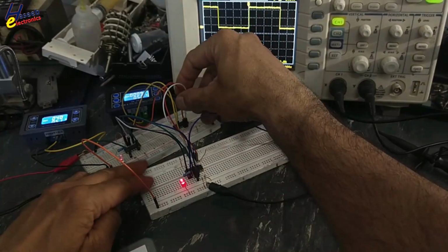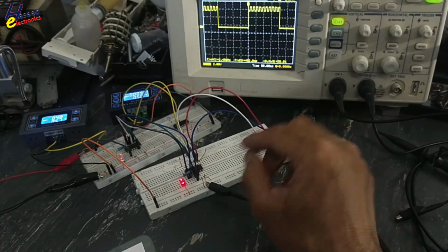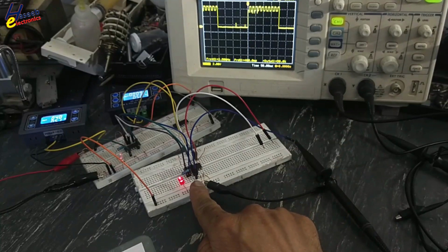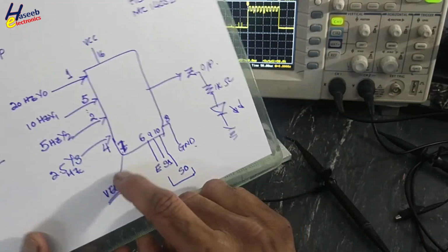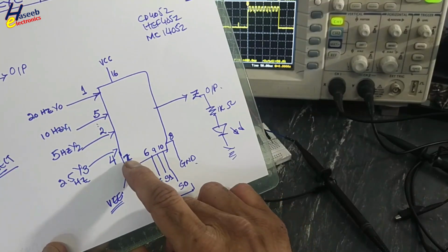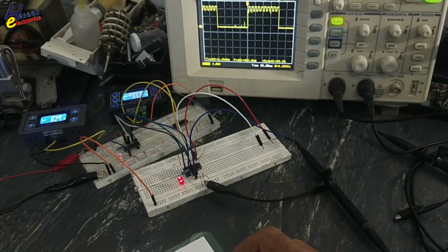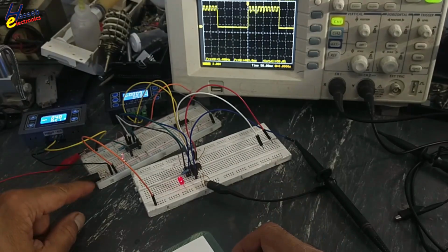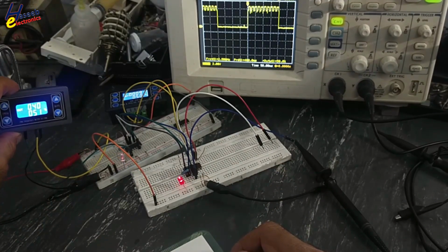And now I have these control signals. I connected pins number 6, 7, 8 to the low side, that is VEE, enable signals, because I am using a single supply to power up these modules. Here I am using a PWM generator module.